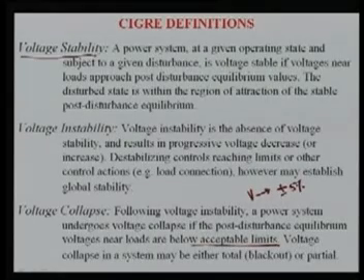So they are connected. So what happens? There may be a possibility that a portion of this whole northern region is out, in dark, blackout. So it is called partial. If the whole region has gone, then it is a complete blackout. Even if only some feeders feeding a village, an area, a municipality or an urban area have gone due to instability and other problems, then it is called partial. So this voltage collapse may be partial or complete, again due to the voltage being beyond the acceptable limits.